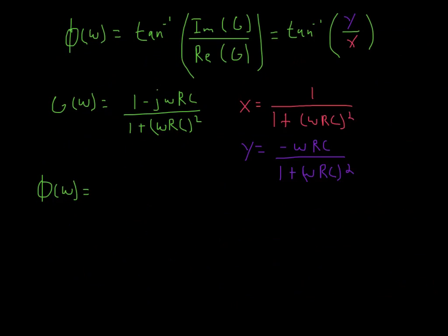Okay, let's quickly look at the phase. And again, this would be how much a sine wave of a certain frequency lags or leads the input that you put in. So on this low-pass filter, we're going to put in a sine wave, say of, I don't know, 1 kilohertz, and we want to see for that frequency, the sine wave that comes out compared to the original, is it ahead of the original or is it behind the original? And this is very real and something we can measure as well, and we want to measure.